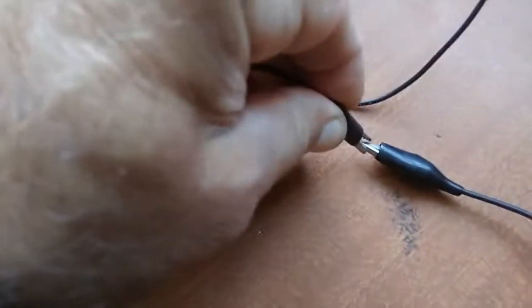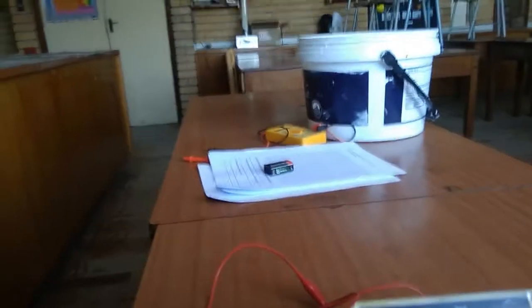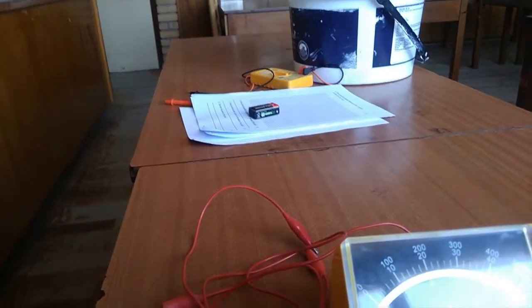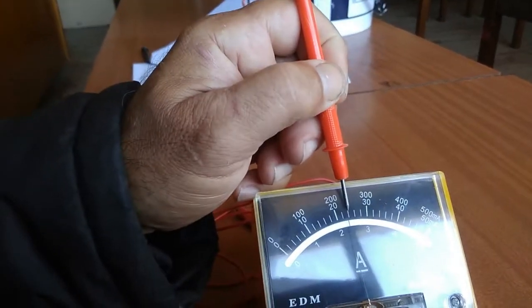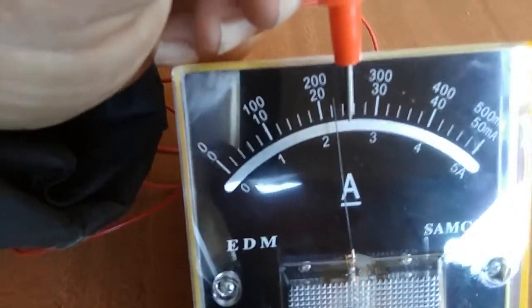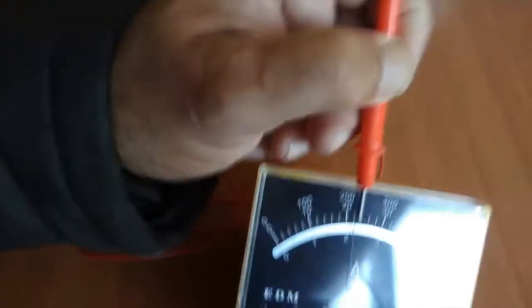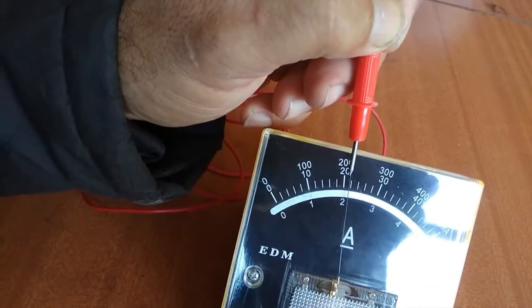So all that's left for us to do is to close the switch. So let's just close the switch, and you will see our ammeter is measuring something. Now our ammeter is set on 5 amps, so we're measuring along the bottom scale there. We always choose the maximum because we don't know. I hope you can see it, there is the needle of the ammeter. It's gone there. It's sinking a little bit. It seems to be sinking as we speak.